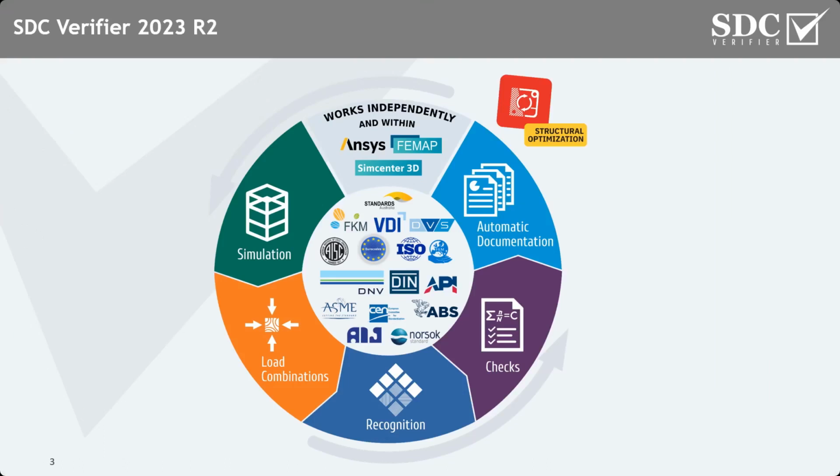At the first step of the workflow, you build your FEA model in your FEA software by importing geometry, building new geometry, meshing it, and doing the analysis. So the model is solved in the ANSYS or Siemens environment, and SDC post-processes the result. In the second step, we combine the loads because multiple loading conditions have to be evaluated. We need to define the number of cycles, the safety factors, coefficients, etc. So we can combine as many load combinations as necessary to perform the verification of standards. Afterward, you can check the result of every individual load, combination or envelope set and present those results.